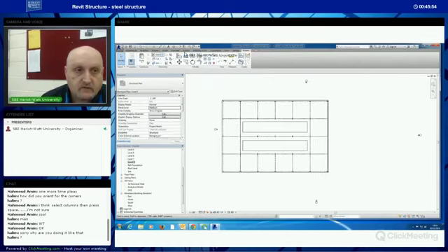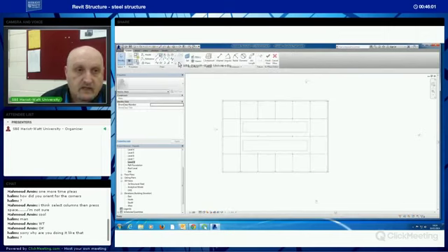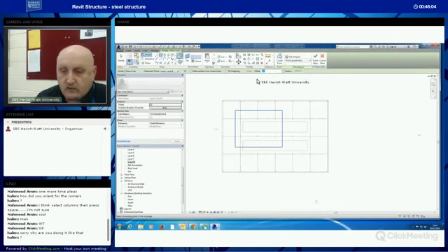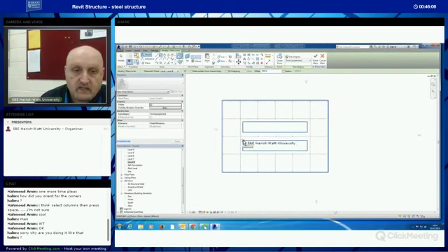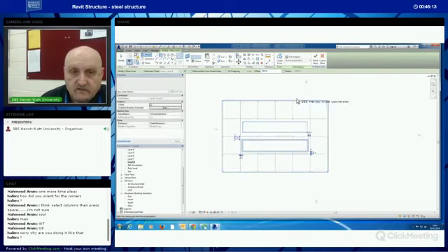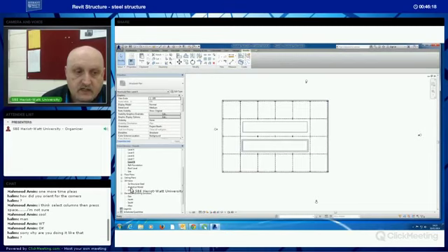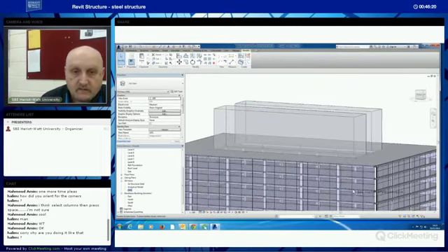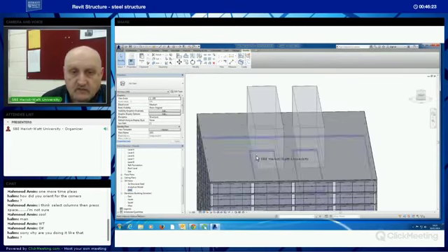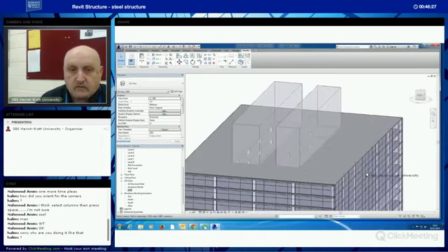I'll make them different. So again, massing in site, in place mass. This is the 4th one we're doing. And this time, again a rectangle, but this time I'll put in an offset. I'll make it the usual half meter offset. And then I simply, again, select exactly on the corners, but this time you'll see it's taken the offset. So create the form, and then finish the mass. And you'll see, ideally, these two masses would be the same, but clearly one is offset on the floor, or the roof, and one is not.